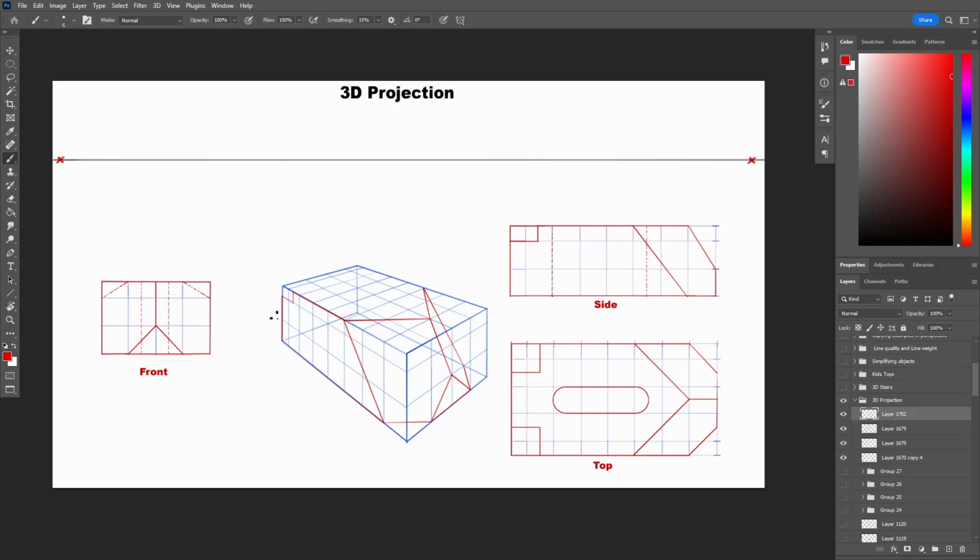Let's now finish up the top view of the object. The holes are on both sides in the back, but with the solid object in between. Each hole is 1 unit wide, but the back end of it is on a slope, as we can see from the front view. So it's straight in the front and slanted in the back. So let's do the area in between and then close it in the back with a slope. The other side won't show, so it will be just a rectangle there. Finally, I connect between the front and the top to close up the object.